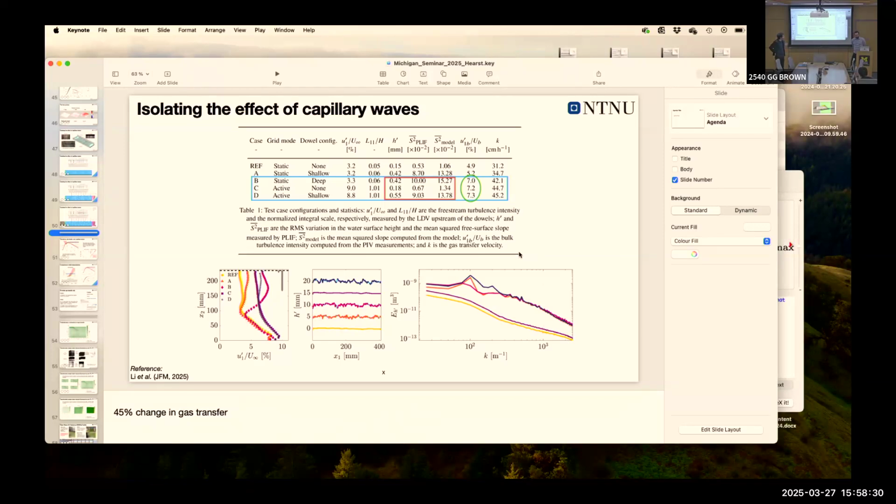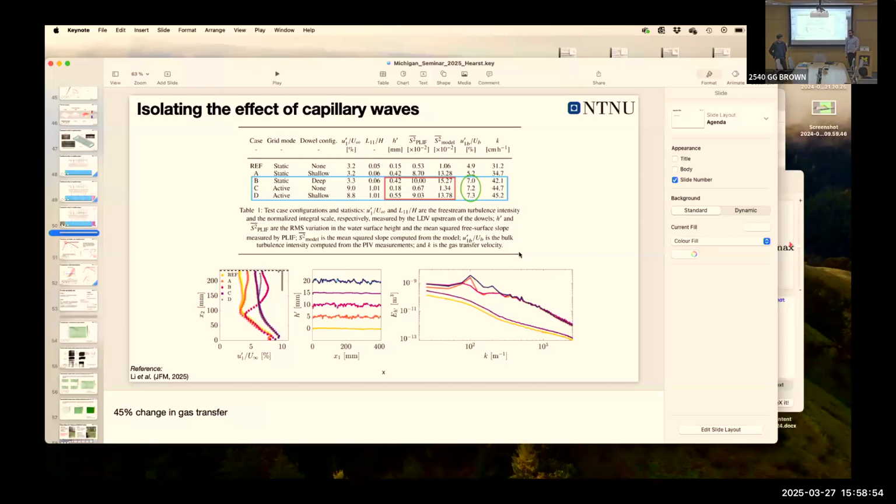But it's broadly a pretty good technique and it's pretty robust. And it's pretty simple if you're doing PIV, because rhodamine just fluoresces with the same laser you do PIV with, and you just need to put some bandpass filters on your cameras to separate them from each other.